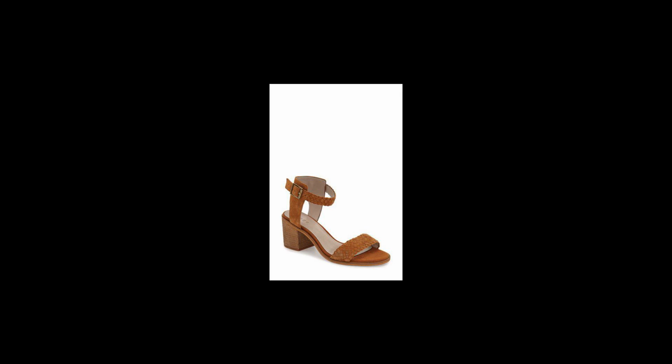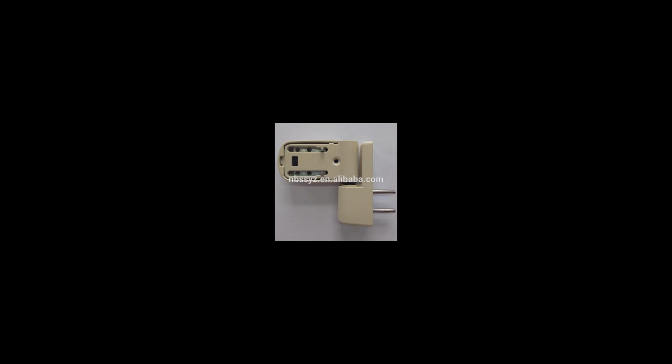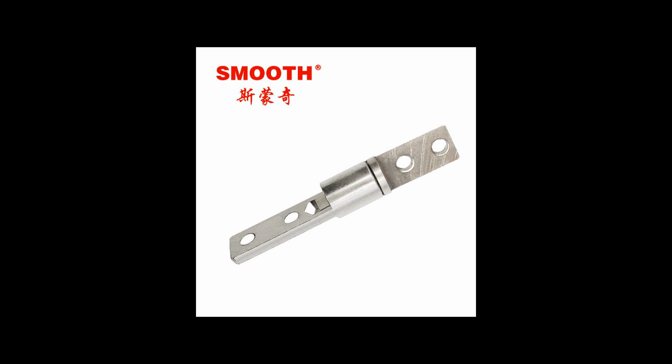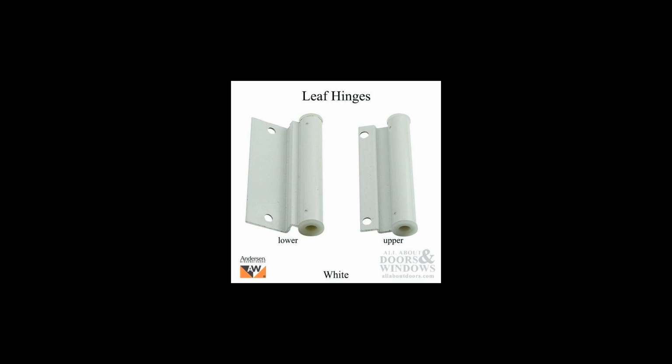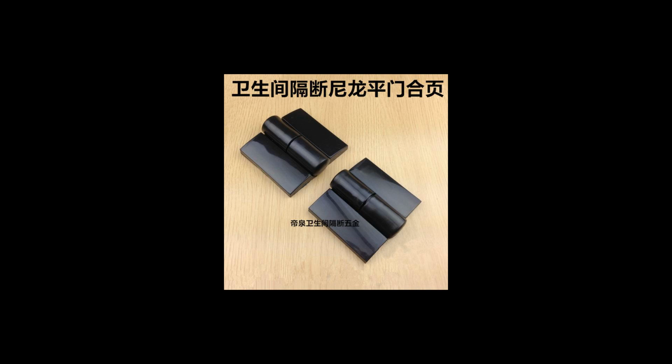Since at least medieval times there have been hinges on drawbridges for defensive purposes for fortified buildings. Hinges are used in contemporary architecture where building settlement can be expected over the life of the building. For example, the Dakin Building in Brisbane, California, was designed with its entrance ramp on a large hinge to allow settlement of the building built on piles over bay mud. This device was effective until October 2006, when it was replaced due to damage and excessive ramp slope.